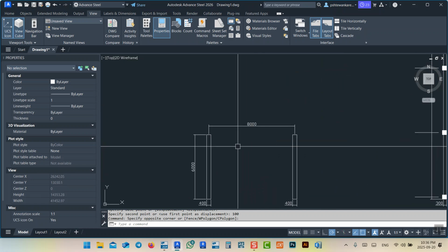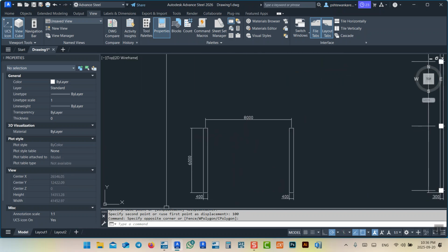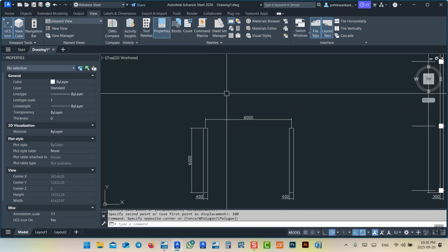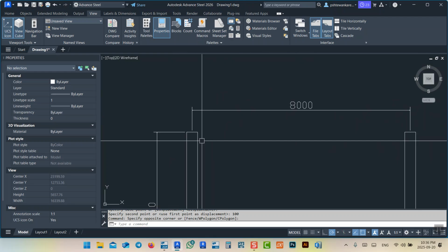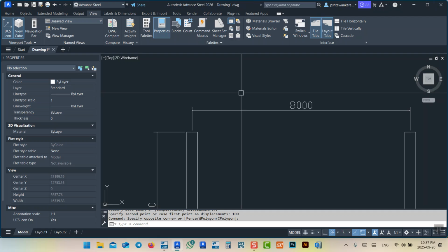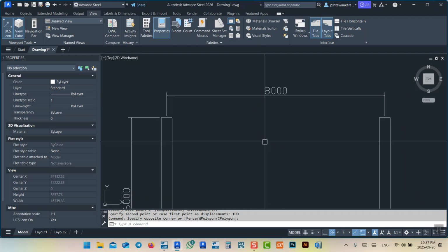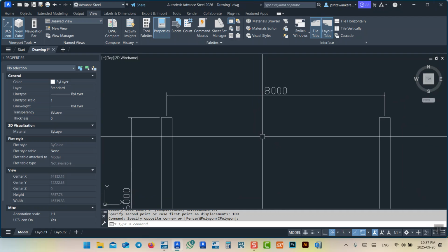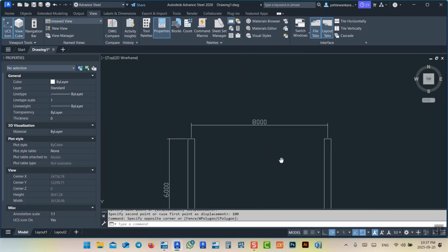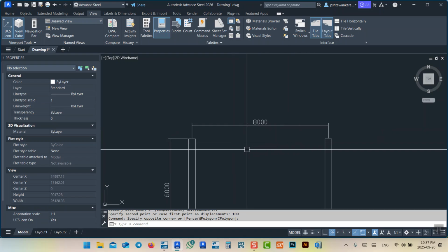Of course, making skylights may be easy. We can make a curved beam like this, but if we put glass, sometimes we need to make triangles so the glass can fit on the surface exactly, if we don't want to bend the glass shape. So first of all, we have to decide which kind of structure we want, or what shape we want.